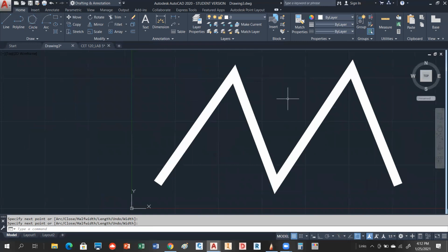Okay, has everybody seen how that works? Exactly the same width option that you were seeing in the rectangle command. It's working similarly in the polyline. The only difference is that you can taper the width when you create polylines, and you can't do that in the rectangle. The rectangle is going to be a constant width for all objects. Okay, is everybody okay with that?